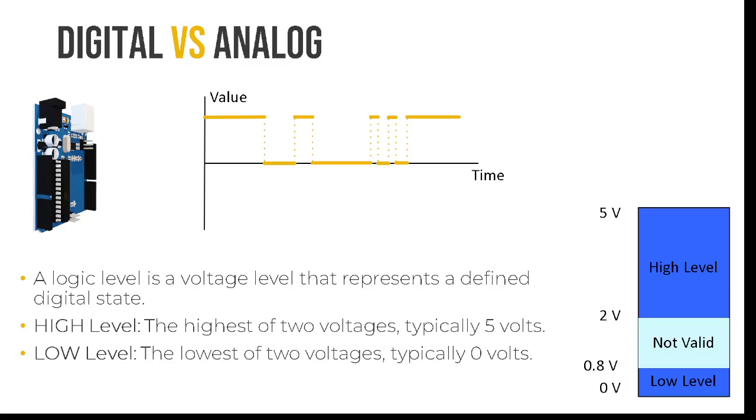Normally, we use some circuits that allow us to communicate with that, right? And that transforms our 5 volt signal to 3.3 and transforms the 3.3 signal from the sensor to 5. That's the move. But if you are just reading something, you could do it with your 5 volts, even if the element that you are connecting is 3.3 volts. Yes.